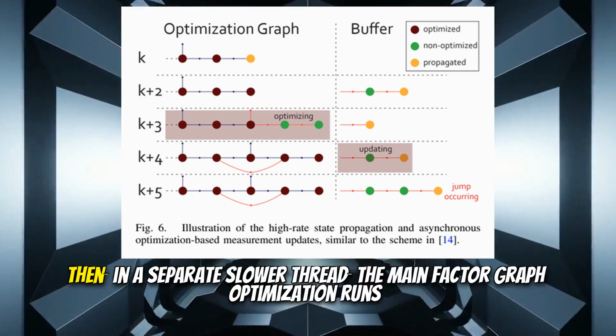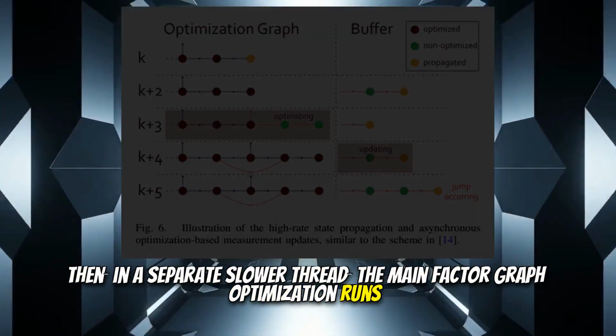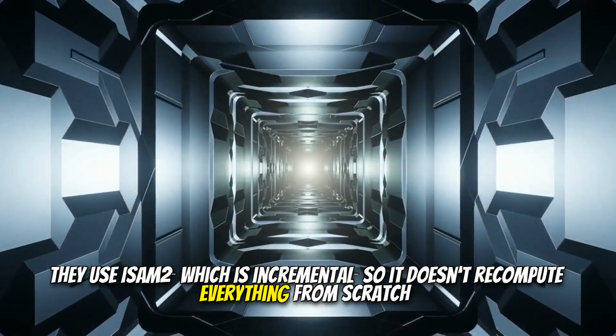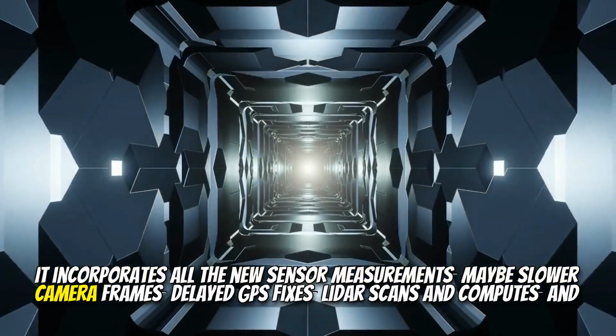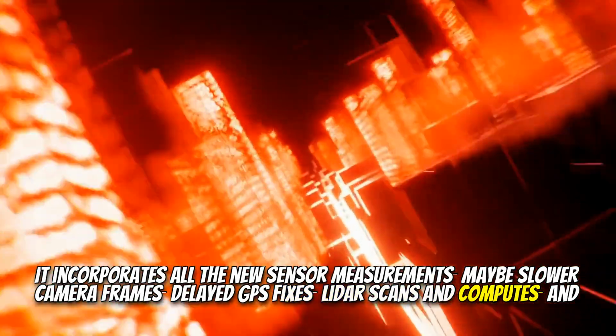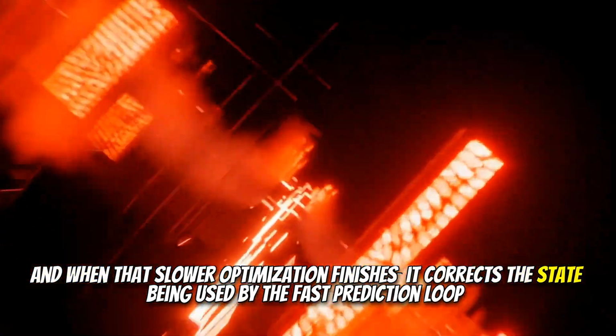Right. Then, in a separate, slower thread, the main factor graph optimization runs. They use ISAM2, which is incremental, so it doesn't recompute everything from scratch. It incorporates all the new sensor measurements, maybe slower camera frames, delayed GPS fixes, LiDAR scans, and computes an updated optimized state. And when that slower optimization finishes, it corrects the state being used by the fast prediction loop. Exactly. The update from the background optimization corrects the trajectory.